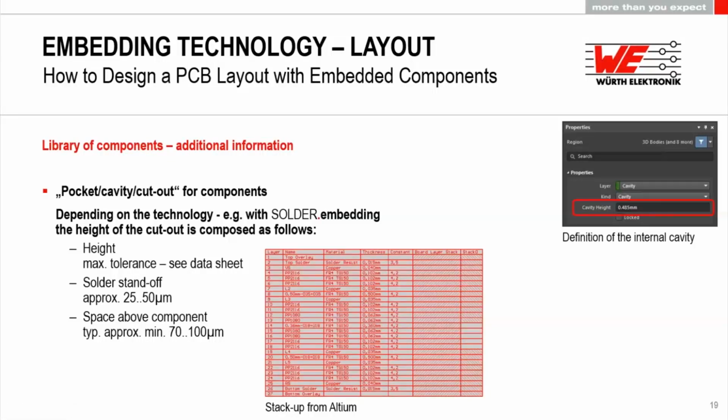And again, in the case of Altium, Altium has the capability to create what they call a managed stack. So when you introduce this cavity in the library and you place the component into your layout and move it down onto here, in that case, layer 4, Altium creates a managed stack here called stack 0, where the cavity actually is shown, and you see which parts of the stack are being affected by this cavity.